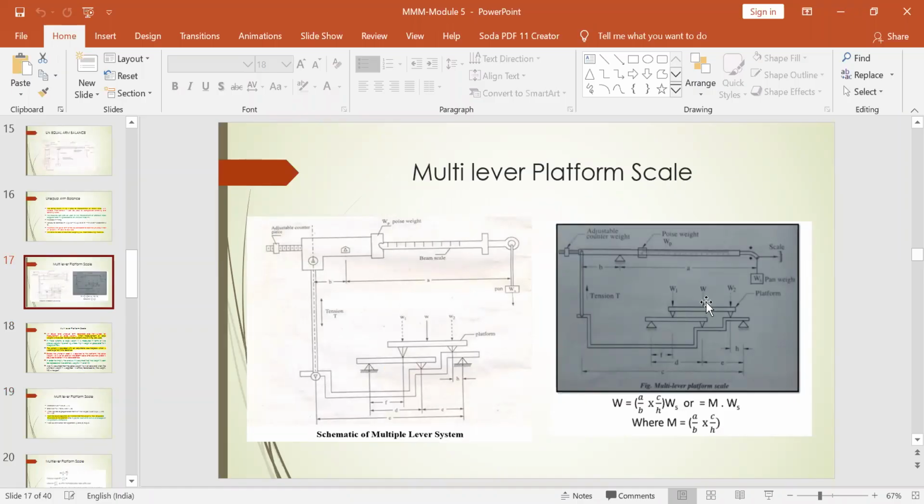You can place the value of W anywhere and just balance it with the balancing arm by adding extra weights to the pan such that the poise weight always remains at 0. This is the constraint we have to follow, and the T value will not come into the picture.